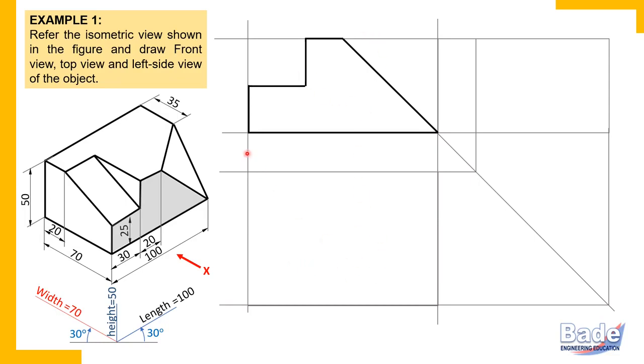So this surface between end projectors, whatever length of this surface from its left end to the right end, from these two ends, you should visualize projectors. The same length of the surface will appear in the top view, and this surface is a line in the top view. So between these two end projectors, I have drawn that line, and that line is on the front.